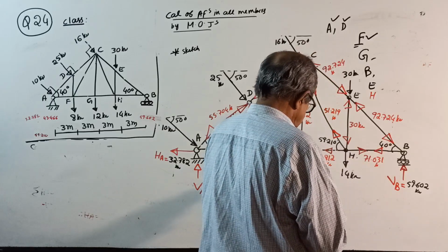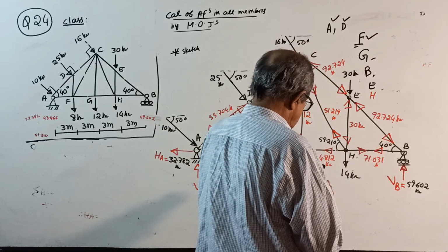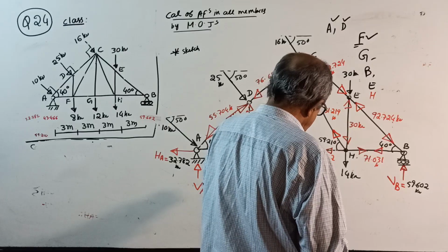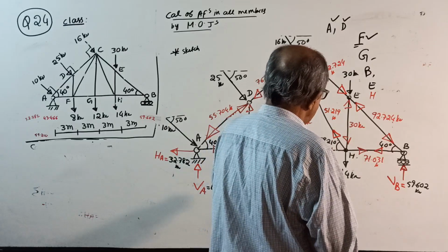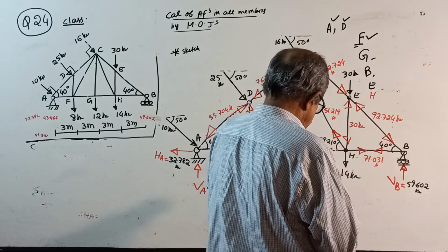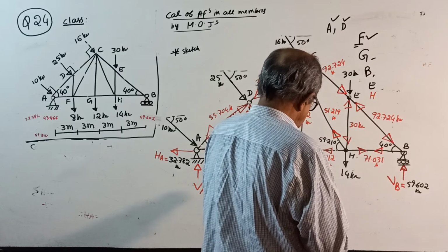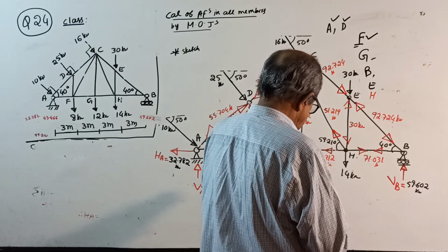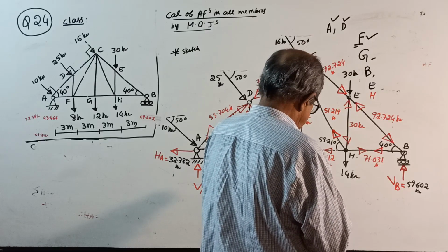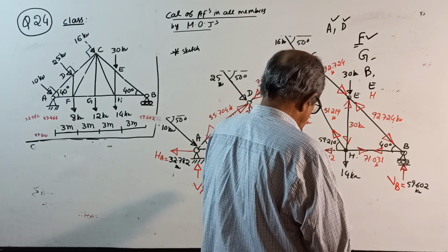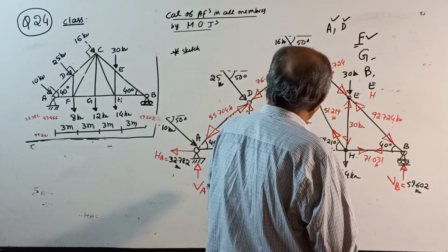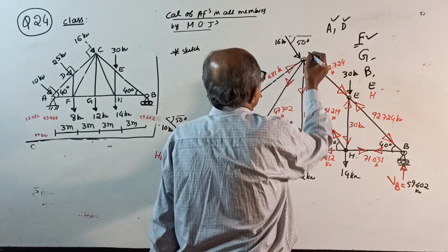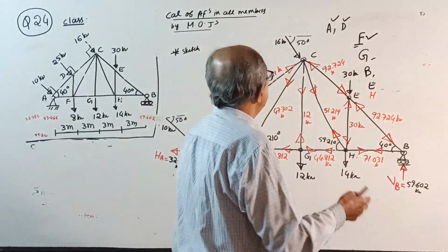Check once again now. 30 plus 14 divided by sine of 59.210 is 51.219. If I do horizontal equilibrium, 71.031 minus 44.812, that answer divided by cos of 59.210 is 51.219. Yes, perfectly tallying. If you want to check, I'll check it now.